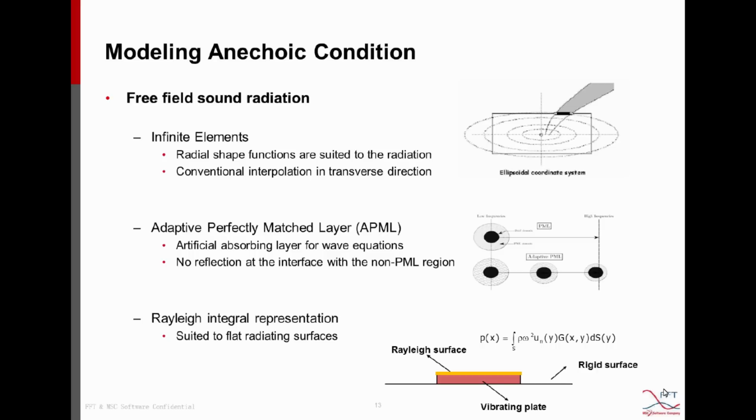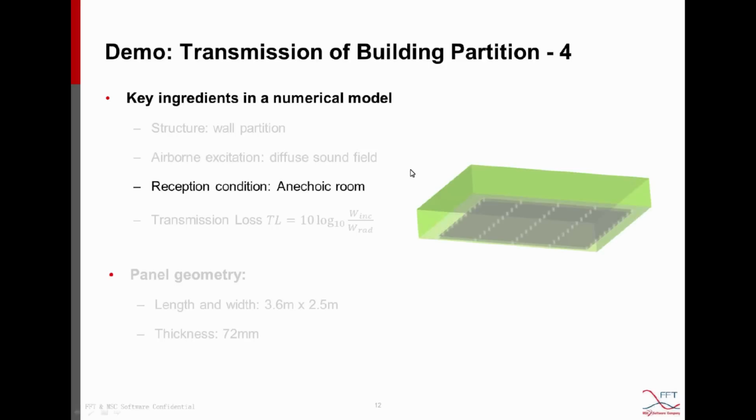There is the adaptive perfectly matched layer technology, or APML technology. For both infinite elements and the APML, a volume mesh will be created, as we can see here in this picture. The volume area is the area enclosed by this green surface. So air will be created inside, and the free field condition will be created on the exterior surface.